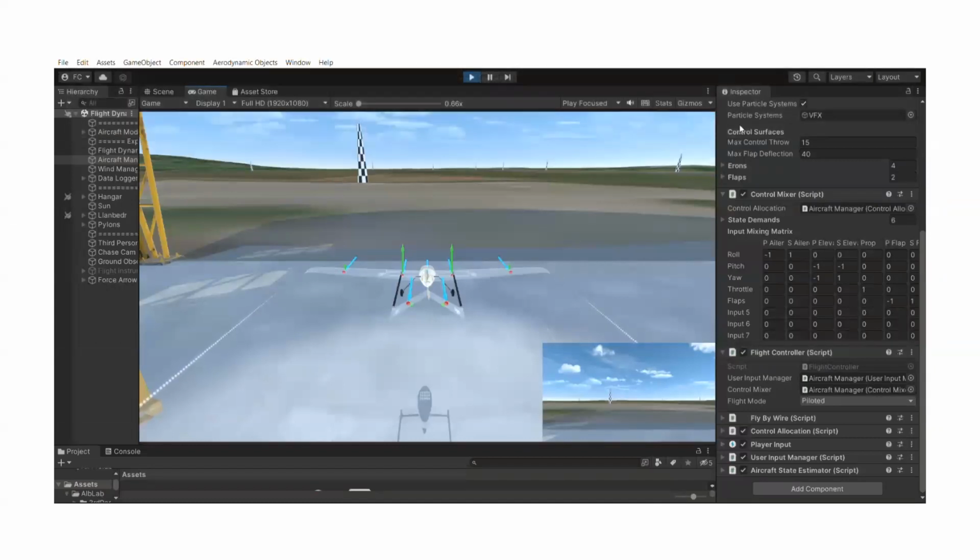Then we move to the sector control. In this one, we're going to try to see if the aircraft is well programmed. So if I put the aircraft to the left, it will go to the left. If I put the flaps down, the flaps will be down. So the first thing we did was a roll. Now we're doing the pitch. Afterwards, we will be doing the yaw. And in the end, we'll do the flaps.